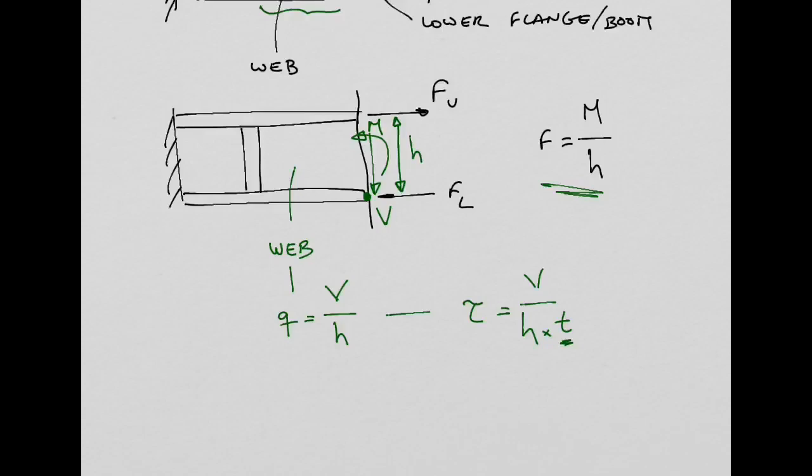You need to compare the stress you get in the web due to the load, which needs to be lower than the maximum stress the material can carry at the yielding point, right? Of course, you can affect this with a factor of safety, yeah. And then we design for a thick web. We design this for yielding, basically, right?